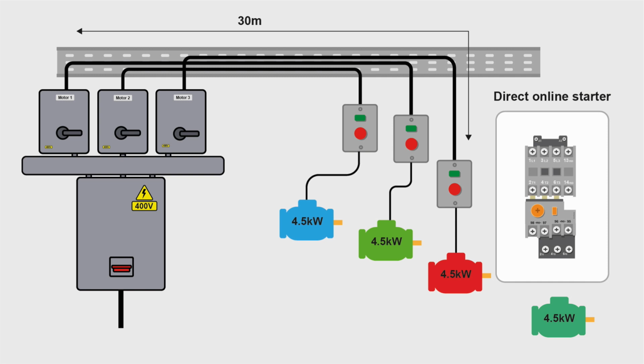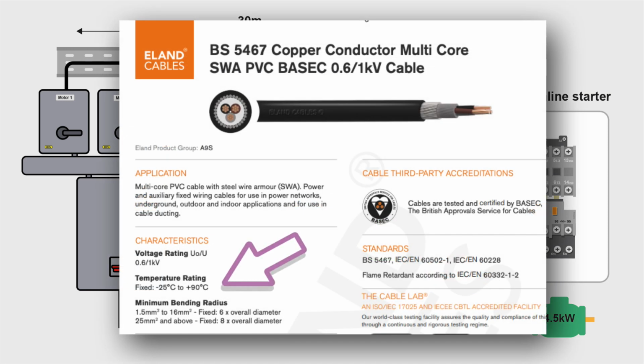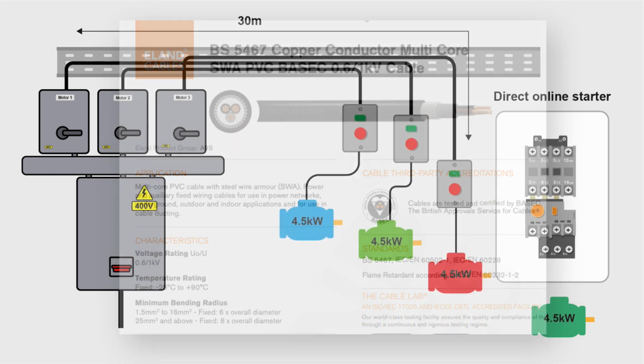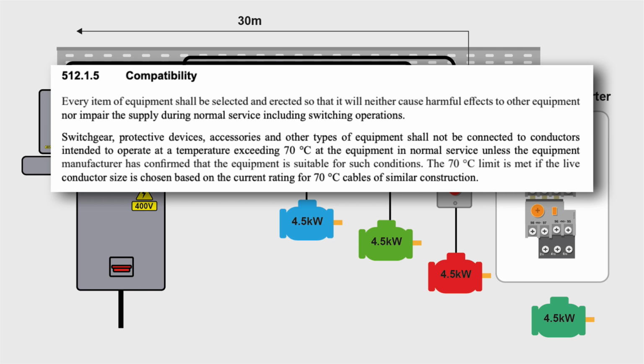A couple of things to mention as well. The SWA you'll be installing will be 90°C SWA. Don't think you can get 70 anymore. We've still got to do the calculated values to 70°C because a lot of our isolators and switches and such are only rated to 70°C.